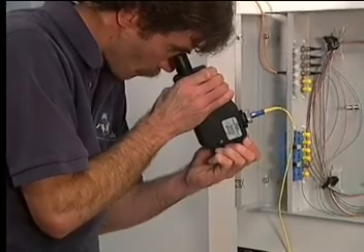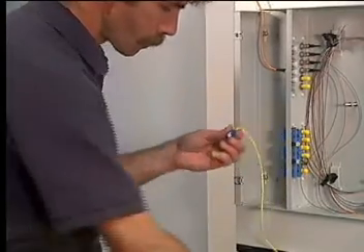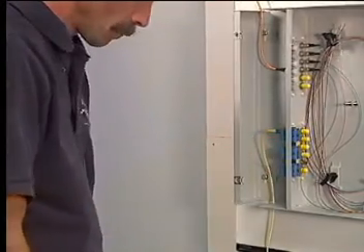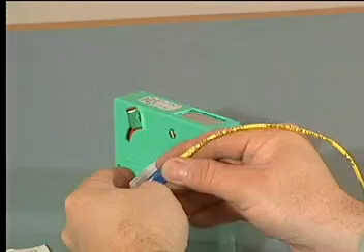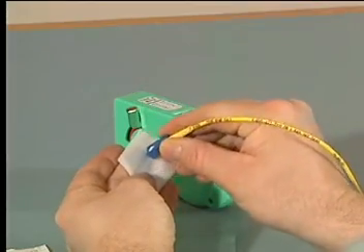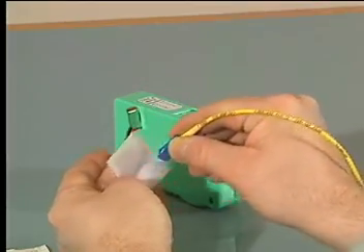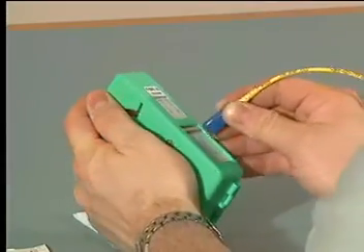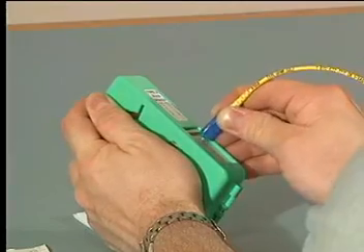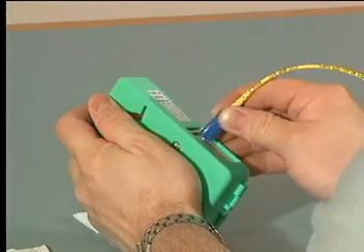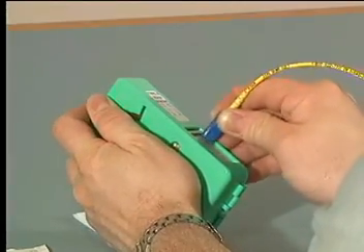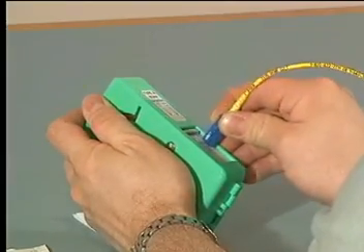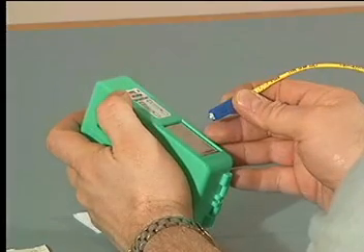Sometimes it may require 3 or 4 cleaning operations on a connector before all contaminants are removed. If the problem still persists, try using an optic pad to wipe the connector ferrule. Then, immediately use the cleaning cassette 3 or 4 times to remove the alcohol residue before inspecting the connector again. If the connector cannot be cleaned, you may be seeing ferrule end damage rather than simple contamination. In these cases, the connector must be replaced or repolished.